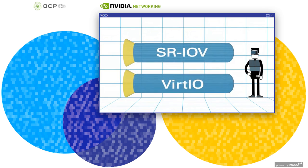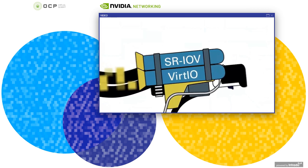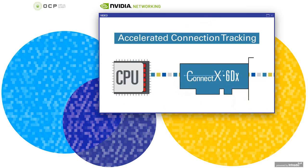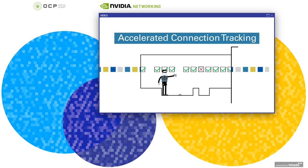The built-in SR-IOV and VirtIO acceleration engines enable a high bandwidth and low latency network interface that's ideal for compute and storage platforms. In addition, ConnectX-6DX supercharges stateful firewalls by accelerating OVS connection tracking with advanced ASAP² technology.